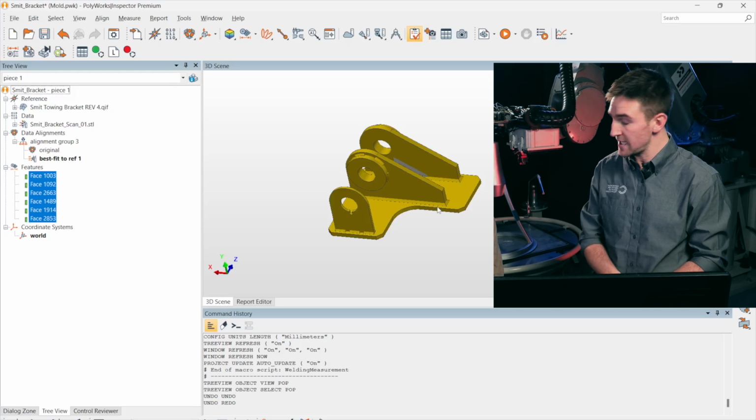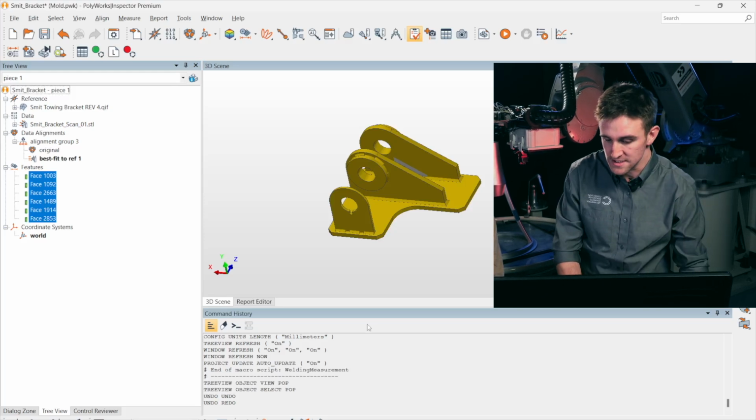Yeah, it's taking all that QIF metadata and using it to determine what to inspect. So a few things like the fillet, the size of it, the length of it, if it's continuous or not. It's computing all of that, and on top of that, it's allowing me to not have to enter the information, so there's no risk of a typo or user error. We are comparing it against the scan data, and we will now be able to see how well we did.